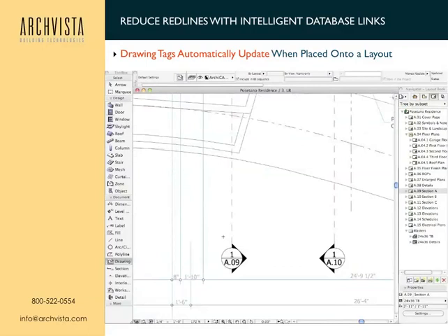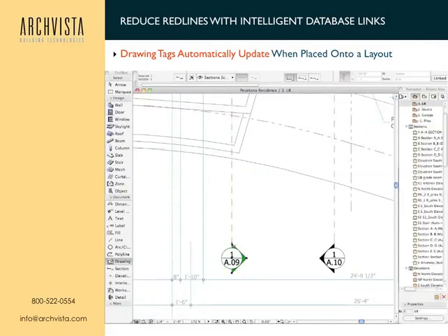Go back to our view, update it, and we can now see that that is now on sheet A09, and it's drawing 1 on that sheet. That's all there is to it. This is the automation that happens behind ArchiCAD as part of a holistic part of the program for updating drawings and layouts, as well as updating the model and the drawings.